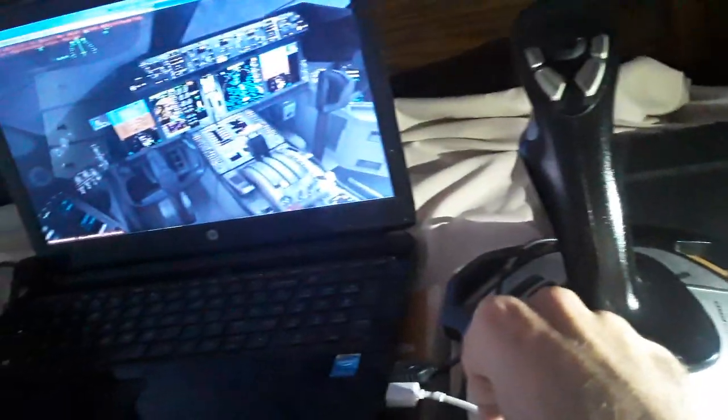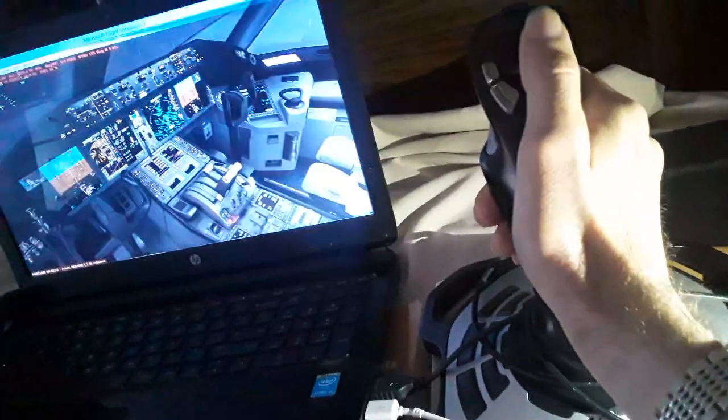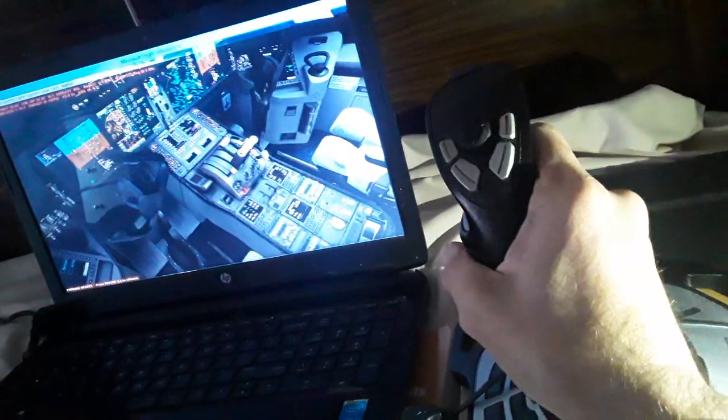So we have it here. So we have the climb and descent here. You can see the side stick movement. So you can climb and descend, and you can also make bank rolls left and bank rolls right. Also use the horizontal trim stabilizer, and use also the thrust levers over here. So you can climb the aircraft, make turns to the left, make turns to the right.